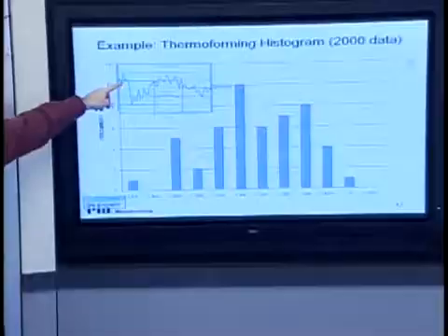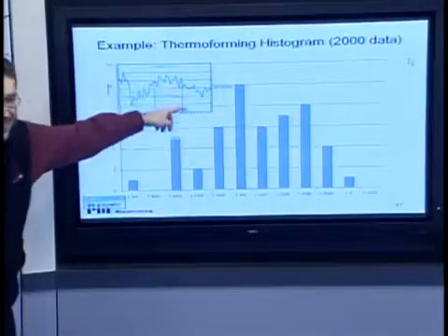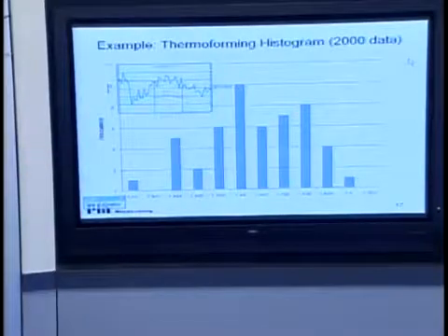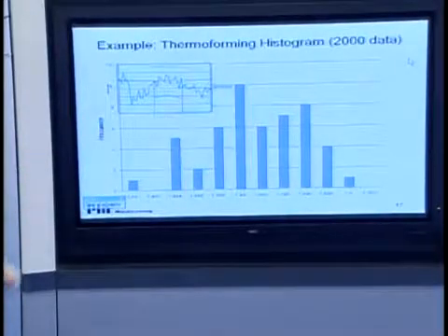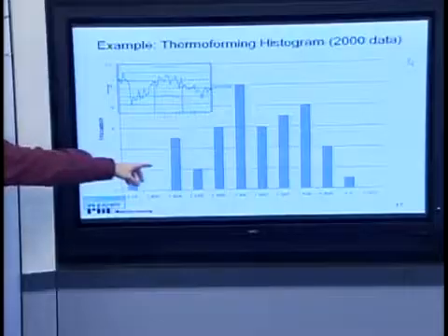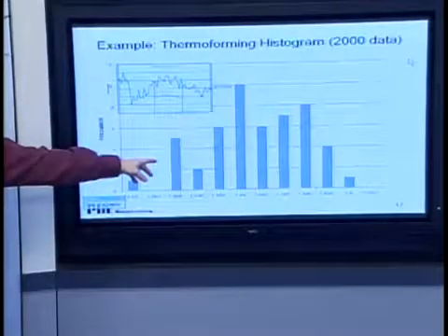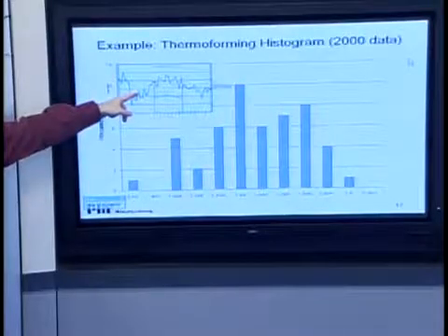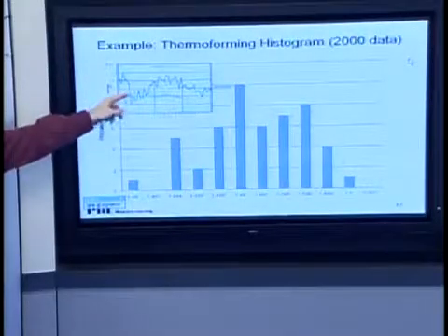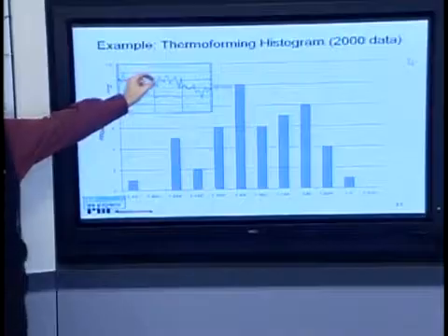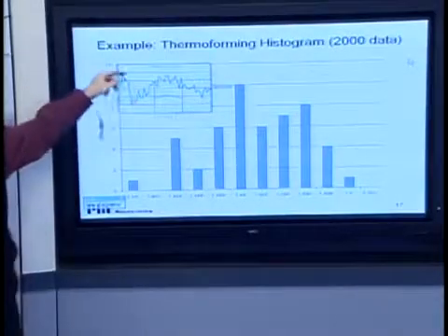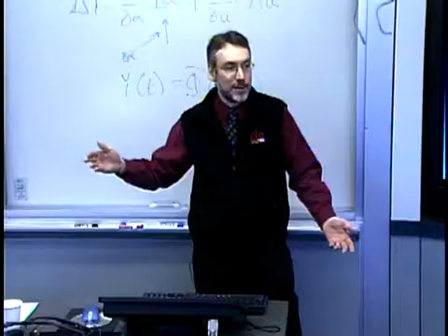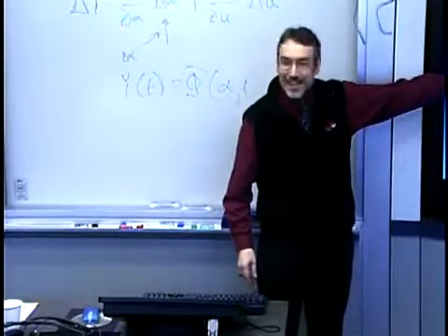Now look back at the data. It's kind of drifting around. So just a peek forward to other things to be cautious about. Don't always believe or just look at your statistics. Always go back to the raw data, because if this were a characteristic of my process, I would say there is a random component, I think, here, but then I'm also seeing maybe some systematic drift that I'd like to go in and squeeze that out.